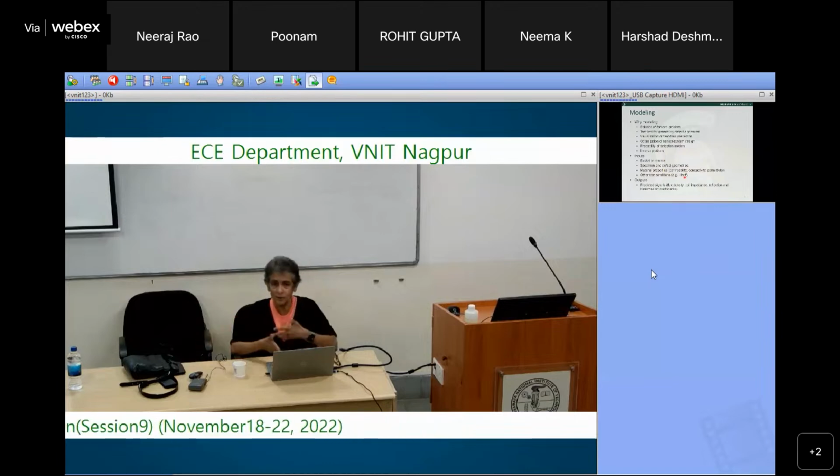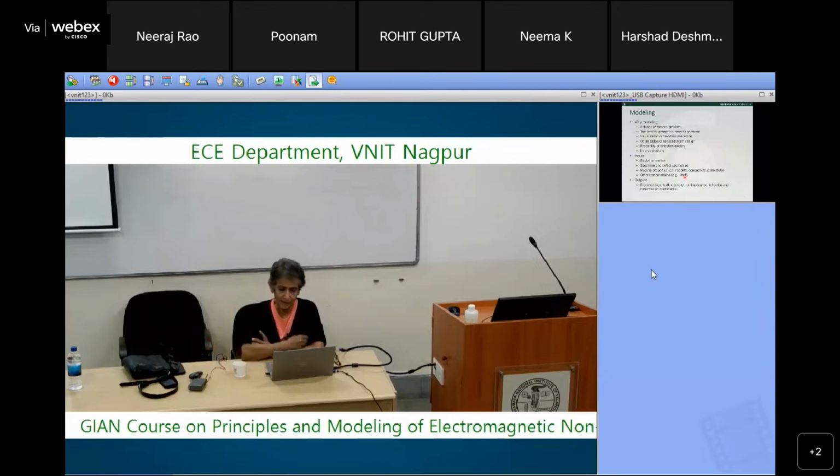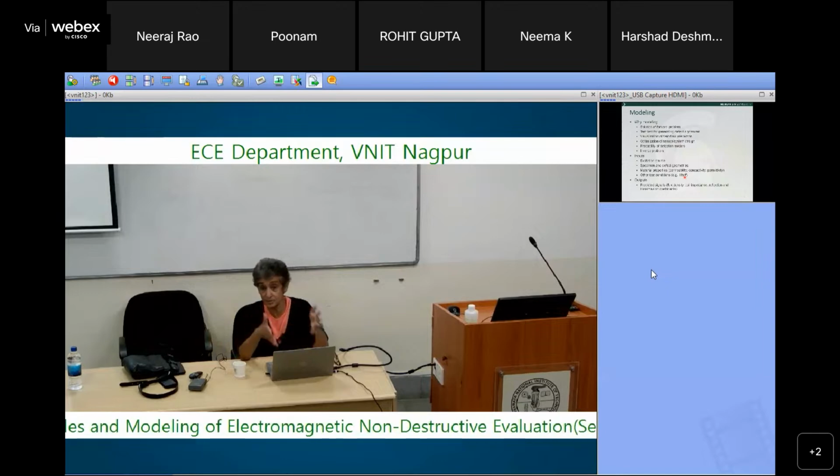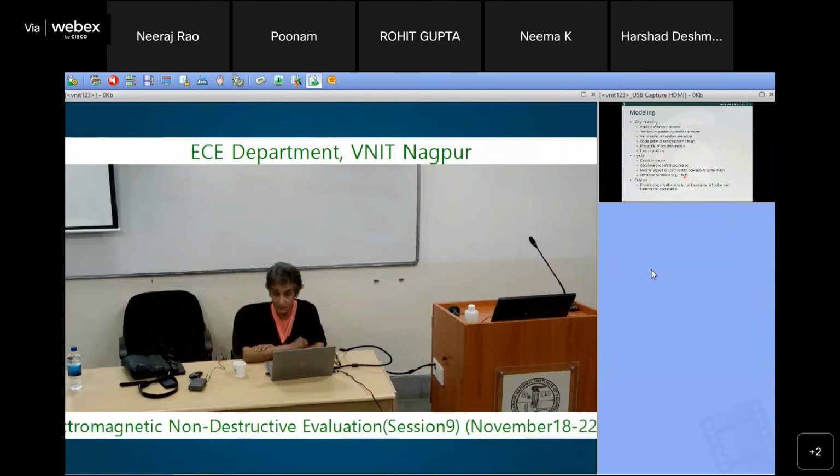We developed another student thesis which was on the probability of detection model. So you have a coil, liftoff can vary, but sometimes it can also tilt. And when it tilts, what happens to the signal? So there is a variety of things, but it's nice to quantify all this using a probability of detection and say this is how the signal is going to change. So we use it extensively.